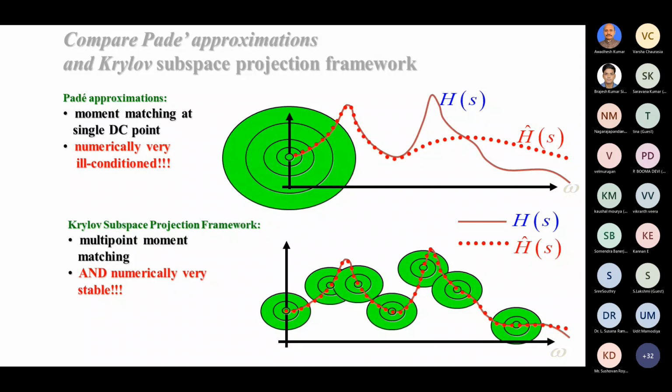This method essentially constructs an orthogonal projection basis from the orthogonalized snapshots, which are obtained during the training. After obtaining the projection matrix from the proper orthogonal decomposition approach, the reduced order models are generated.